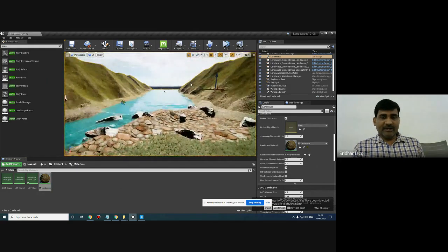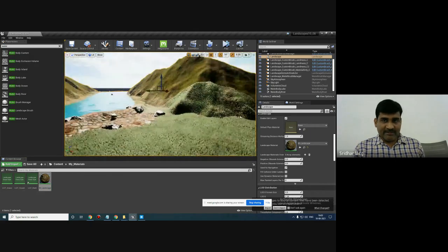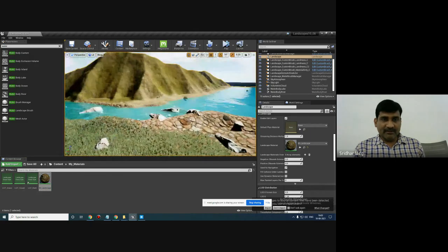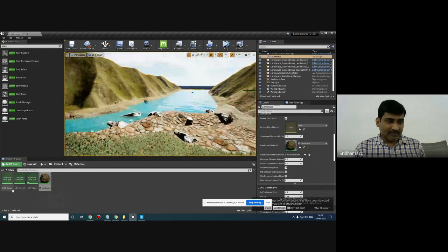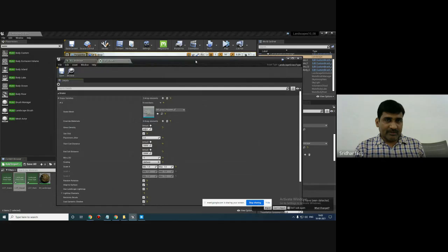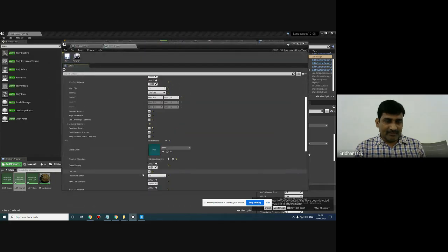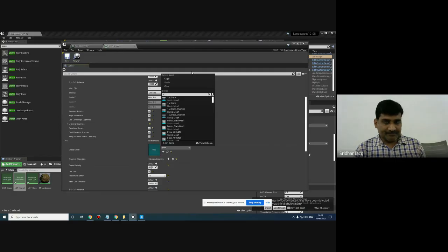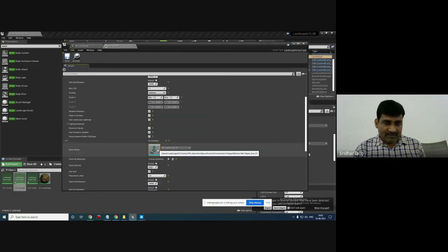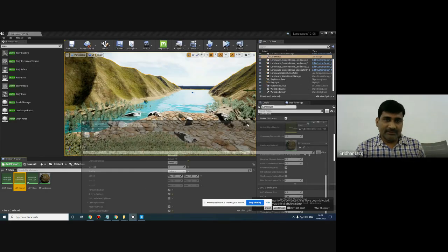If you want to add some trees on it, you can add them where you want, in grass or in gravel. So we'll try in gravel. So where is the gravel? Here is the gravel. So here I will add one more material type. Here I will select tree. Okay, the same popular tree. This is the tree, I think. 400 is too much, so I will add a value of 5. I think 5 also is too much.